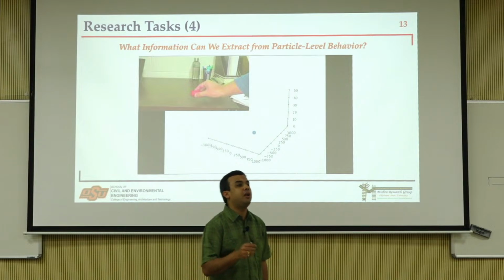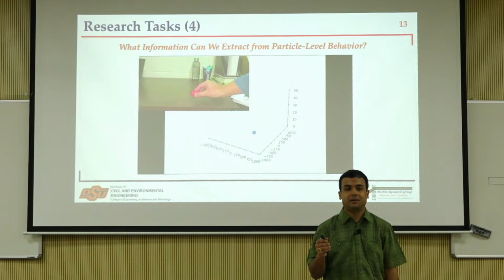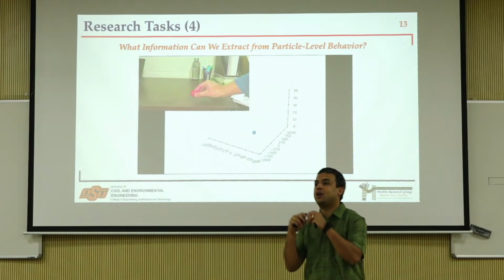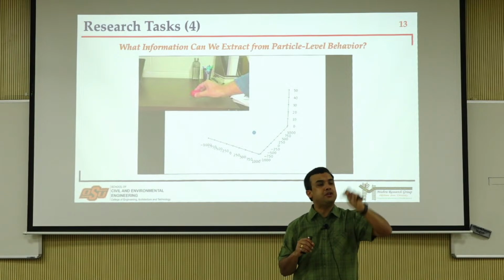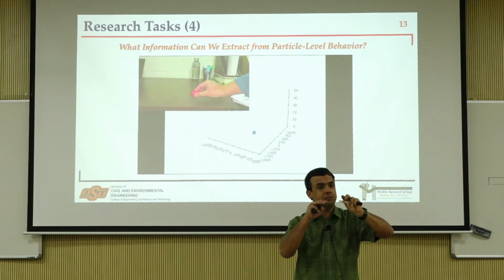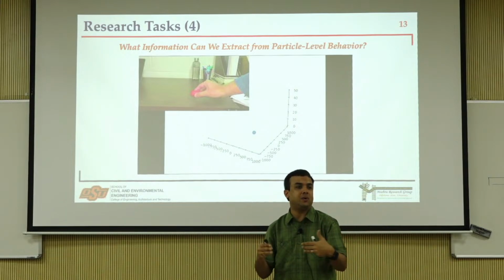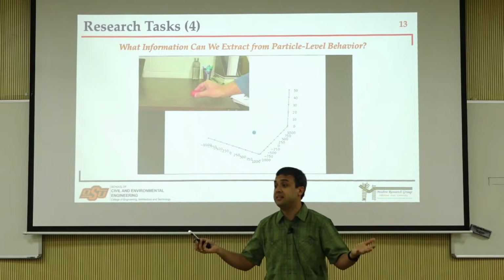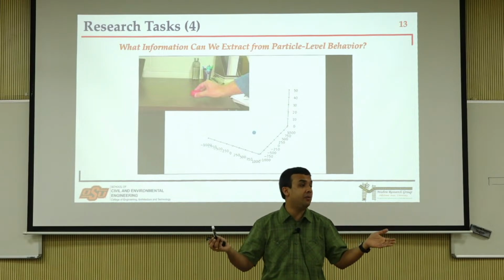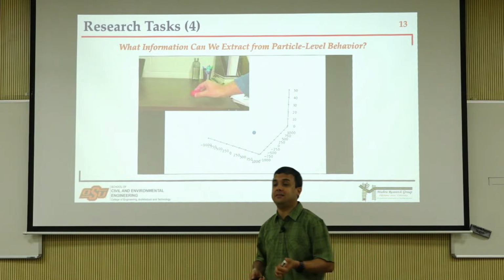Have you all heard of what is known as intelligent compaction? It's basically a compactor that has sensors in it. Okay, so it measures the acceleration of the layer as it compacts, and then it can detect that through check adequacy of compaction. But the problem is, intelligent compaction is very expensive and it is only available for big compactors, right? So then what I said is, these are small projects.